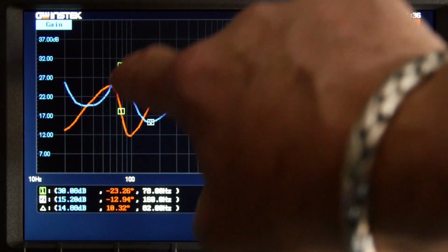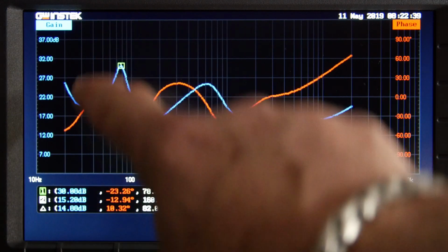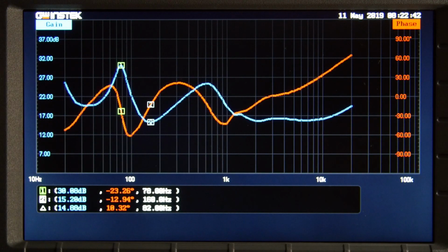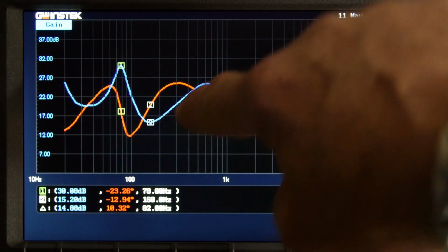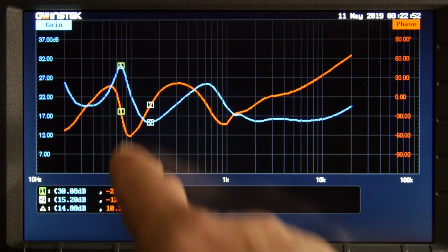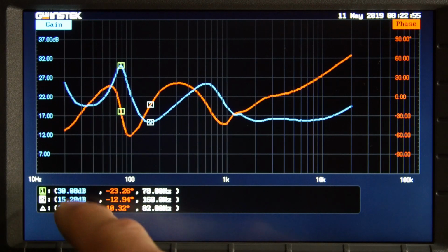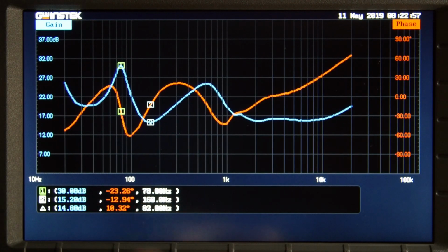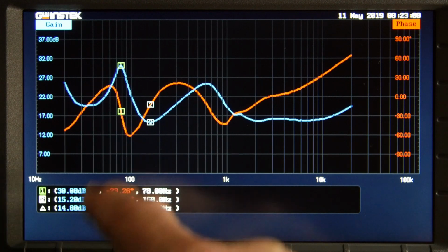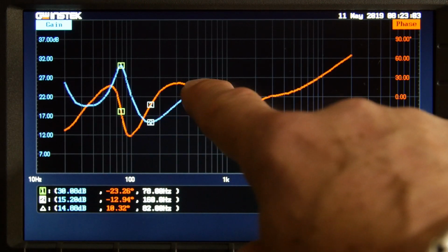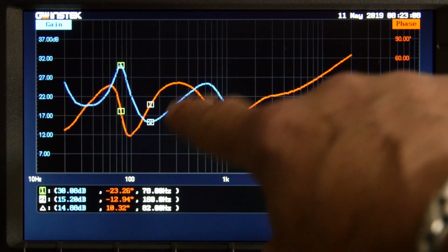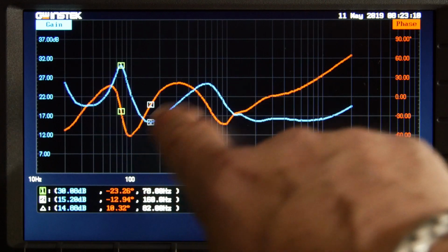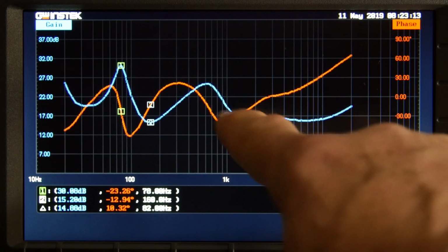And then it comes up pretty sharp, and then it drops sharp. So that's a pretty sharp resonance right there. That happened at 70 hertz. And then it drops, and kind of like this, it's dampened by resistance before it goes inductive again. And that happened at about 160 hertz. Then out here around, let's see, 2, 3, 4, 5, around 600 hertz, it had another resonance. So there's like 1, 2, 3, 4 resonant points, and then another one here.